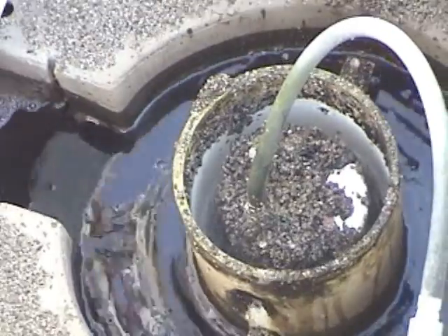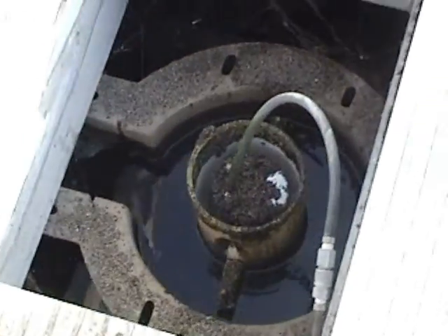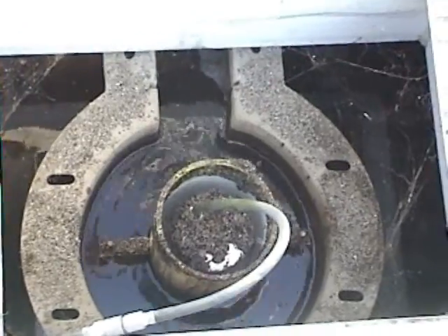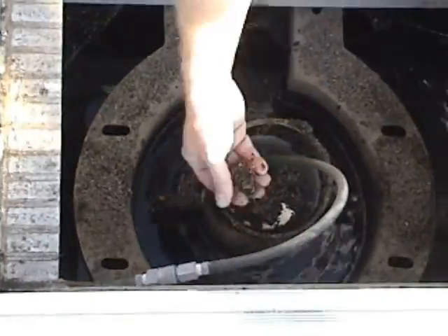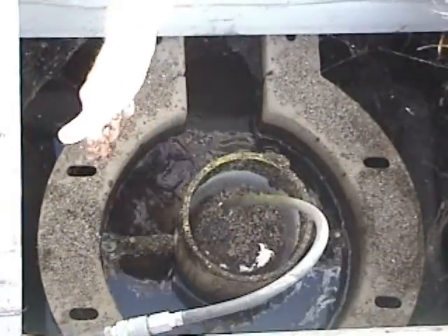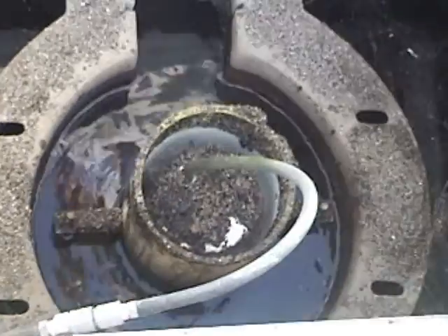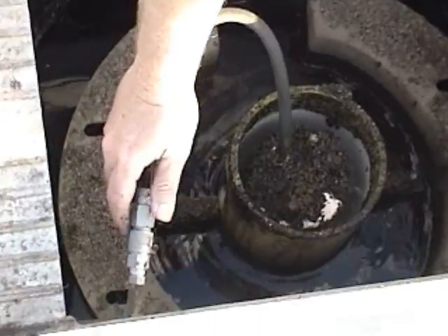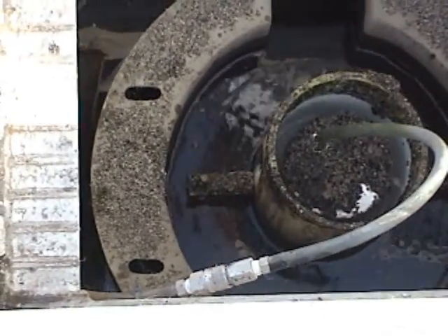by the airlift pump, it goes up through this thing that looks like an electrical insulator. It's got little baffles on it, and it sets up some motion in the water so that it'll shake anything that's trapped on the sand off. And this is the sand that we're looking at. So that's what the filter looks like. If you ever want to service one or pull it off, there's an air line. You just disconnect this right here, and you can pull the whole airlift pump unit off.